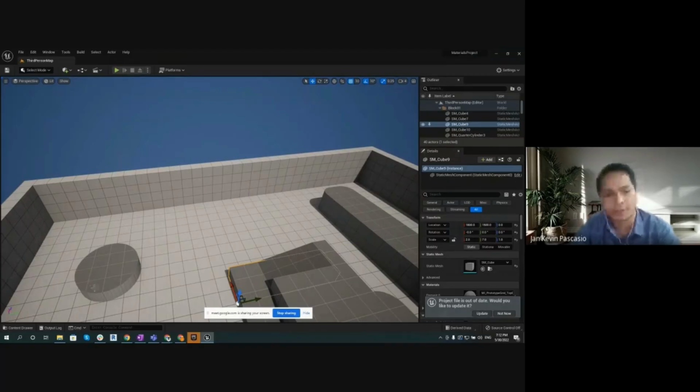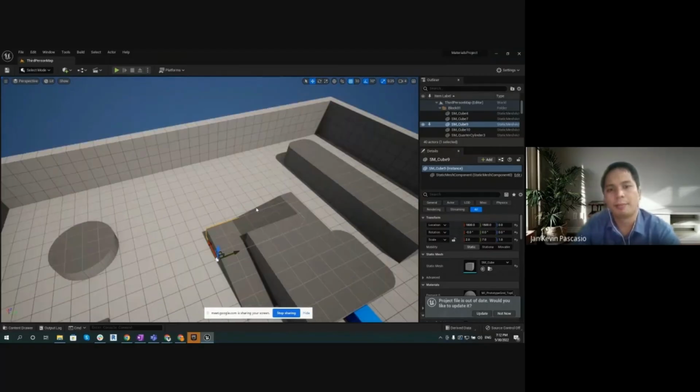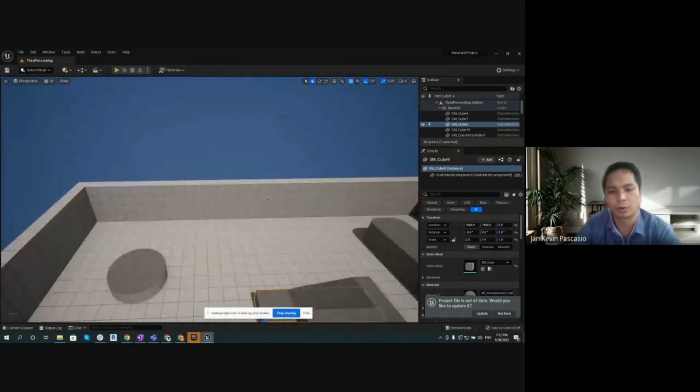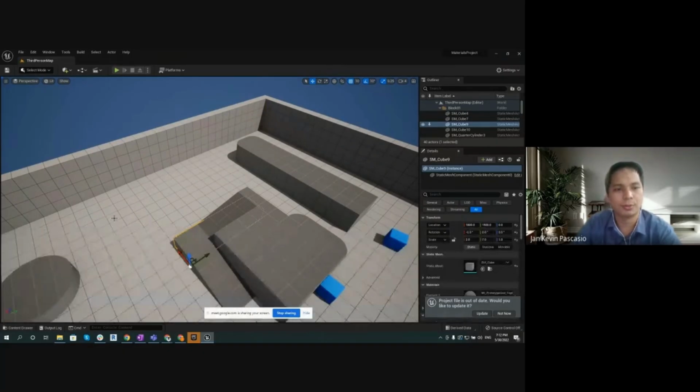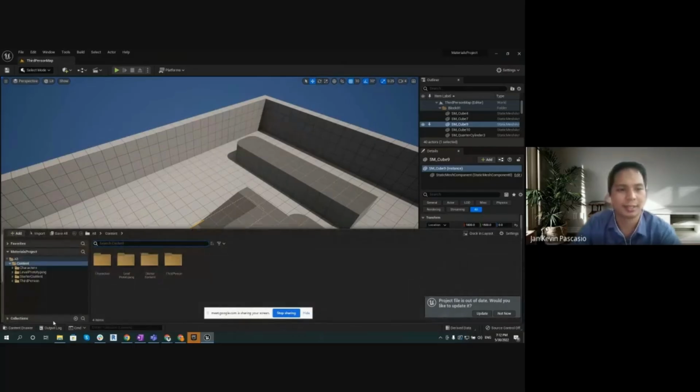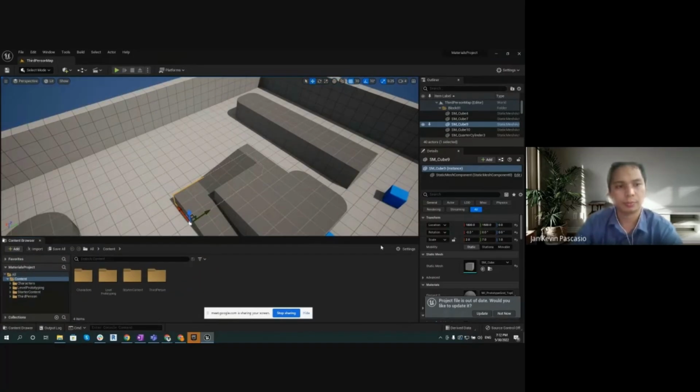It's a new feature of Unreal Engine 5. You can minimize and maximize it by pressing Control and Space. So Control and Space, and it will show up. And Control Space to put it back again here, so it can be easily accessed. Or if you want to dock it, there's an option here to dock in layout. So instead of being a content drawer, it's now called the content browser.